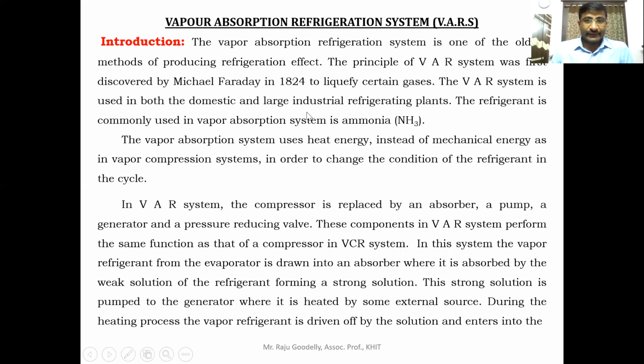Nowadays we are using VCR systems, but in olden days the VAR system was most useful whenever power was not available or power was very expensive. The vapor absorption system uses heat energy instead of mechanical energy as in the VCR system, the vapor compression system.